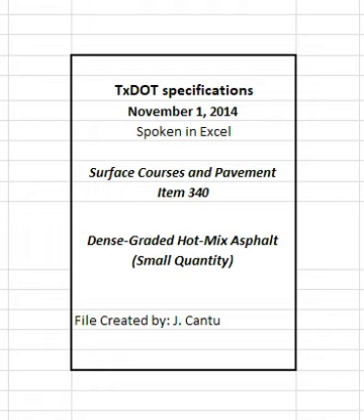4.8.3.1 Voids in mineral aggregates, VMA. The engineer may determine the VMA for any production lot. Take immediate corrective action if the VMA value for any lot is less than the minimum VMA requirement for production listed in Table 8. Suspend production and shipment of the mixture if the engineer's VMA result is more than 0.5% below the minimum VMA requirement for production listed in Table 8.